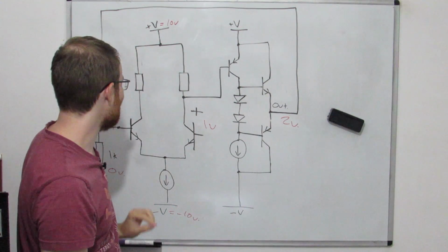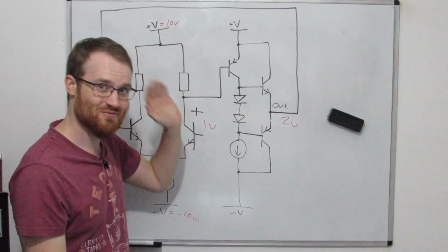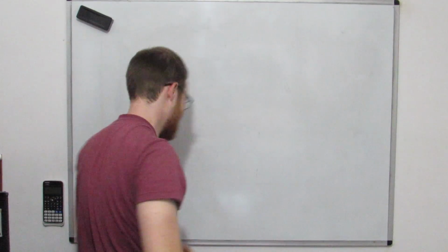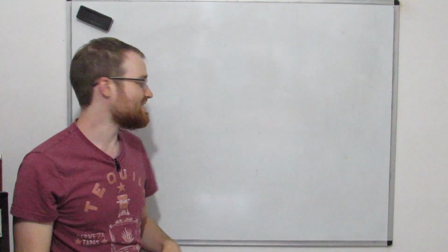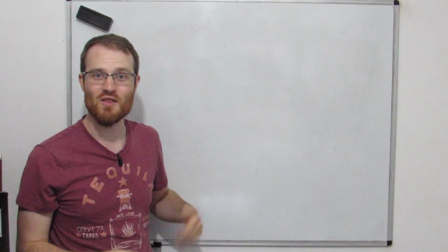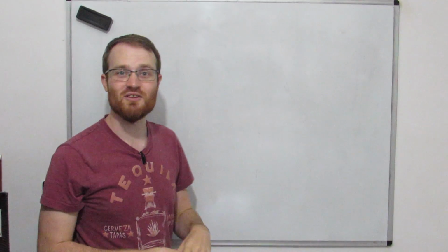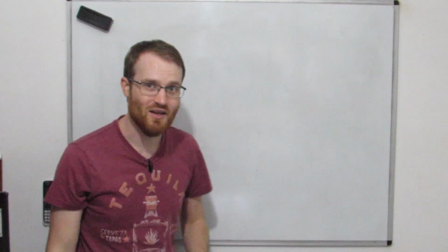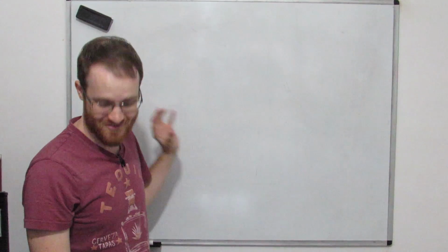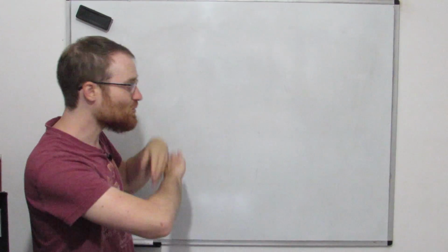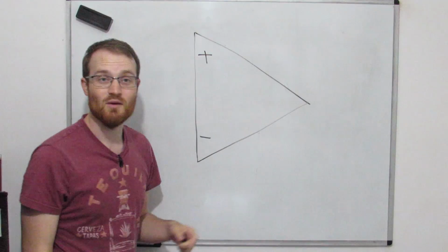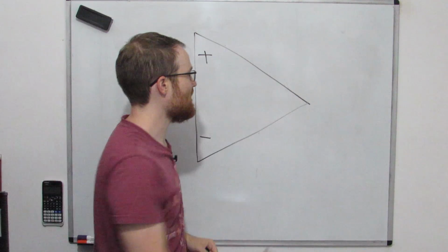What we can do now is we can forget about this. We can forget about those detailed schematics, and we can throw it all in the bin, and we can say, I don't care about how much current is shared from one transistor to another. I don't care about the VBE drops in between the two output transistors. I trust that the IC designers have done their job properly and that all of that is taken care of for me, and I can worry about the two inputs and the one output.